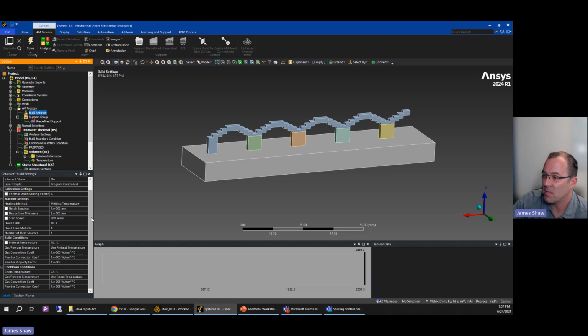And then in our tool here, we have build settings. These build settings on the left are all the settings that we need to put in. They're characteristics of the geometry, characteristics of the print, what comes out of the slicer, the G code, and the environment of the machine. In fact, this particular geometry we did create with our CAD tool, but ultimately you could just directly import the G code, which is really exciting because someone has already invested quite a bit of effort to get the G code through the slicer and ready for print, and all of that information is literally the same information that we need to simulate that print process.